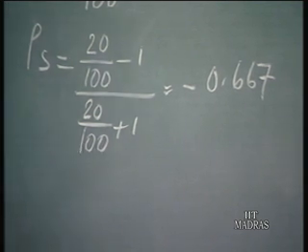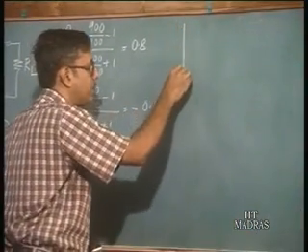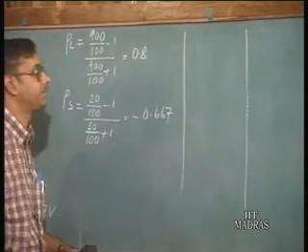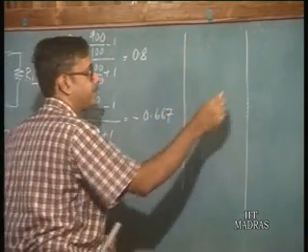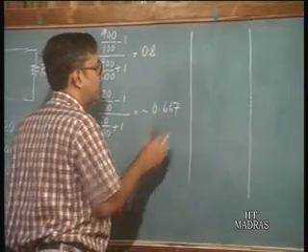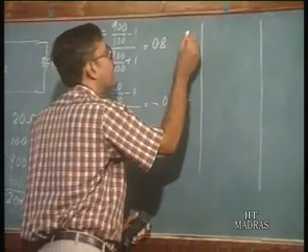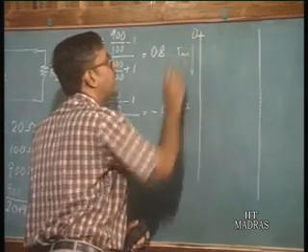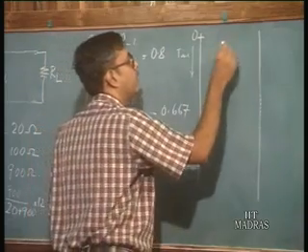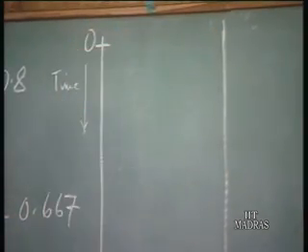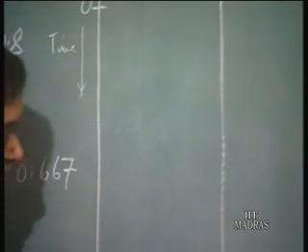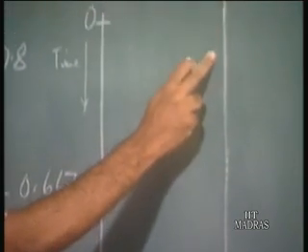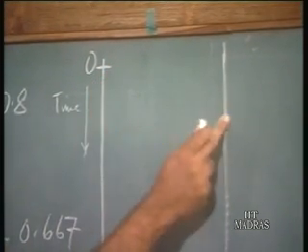These are the reflection coefficients. Now, to find out the waveform, there is a particular diagram which is drawn, like this. Suppose this axis on this side is the time, and this end is 0. This is the source end, and this is the load. It takes a time Td for the waveform to move from the source end to the load end.